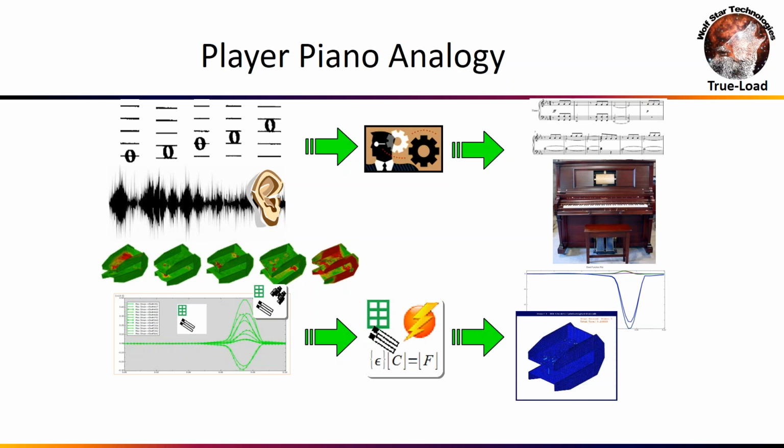So this has a direct parallel to the concept of modal decomposition and modal participation functions. It has a very parallel mathematical approach to a concept that you may be familiar with, modal superposition. This is using basically quasi-static loads to reproduce the full field events.